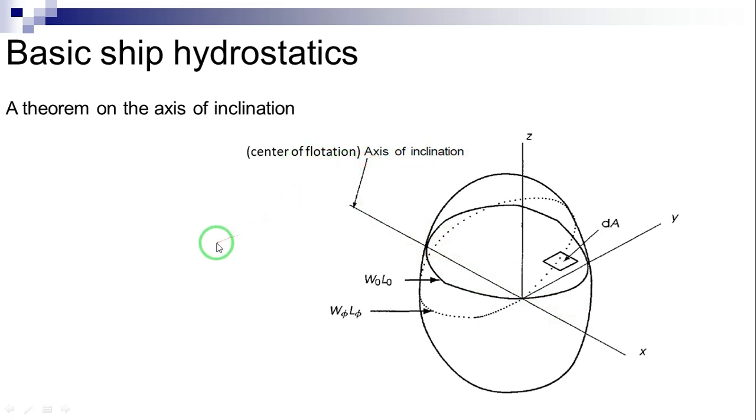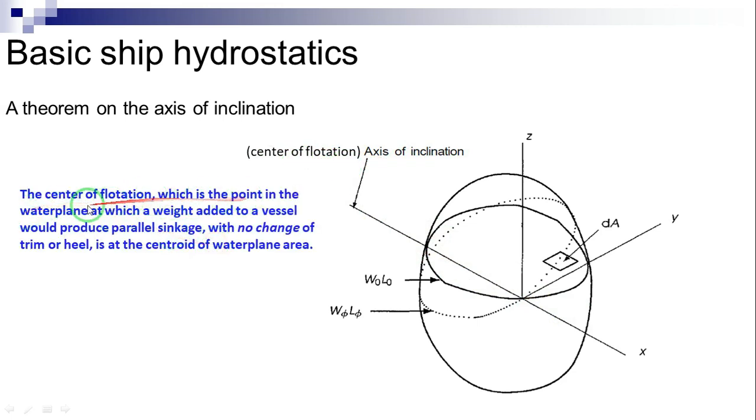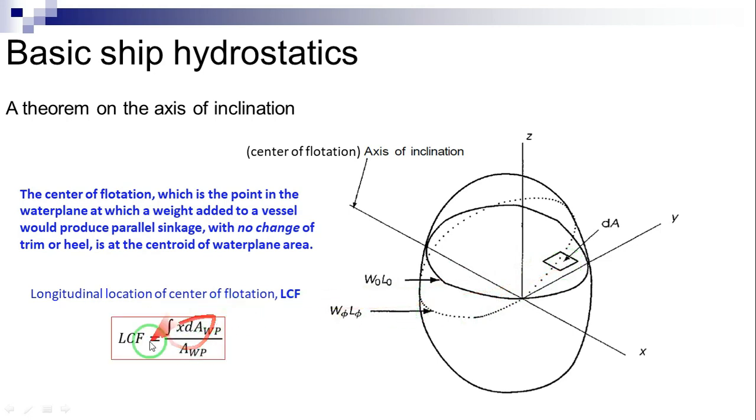The center of flotation, which is the point in the water plane at which a weight added to a vessel would produce parallel sinkage with no change of trim or heel, is at the centroid of water plane area. The longitudinal location of center of flotation, LCF, is found by calculating the longitudinal moment of water plane area in conjunction with the calculation of area as shown here.